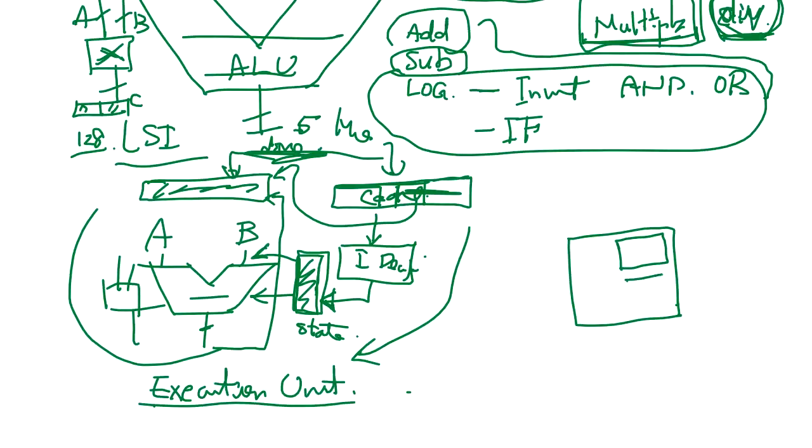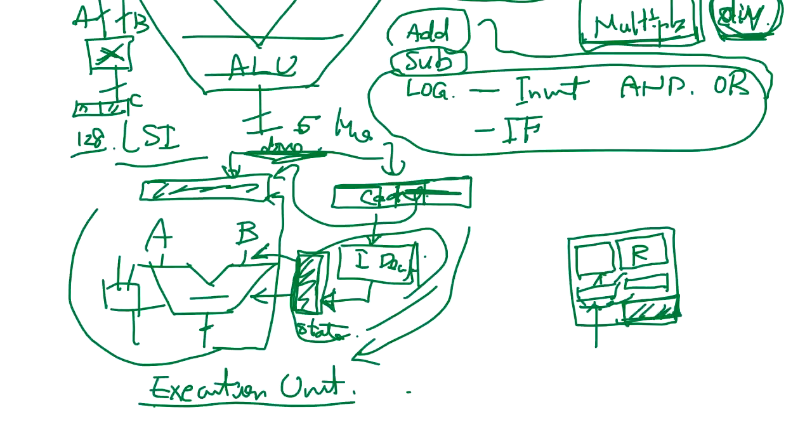The ALU and the multiplier are very big too, very hardware intensive. And there is a cache from memory, and miscellaneous signals. The instruction decoder and state machine are a very tiny portion of the CPU. And if there is an on-chip cache for this register, that's going to be the biggest portion. So that's the conventional CPU chip.